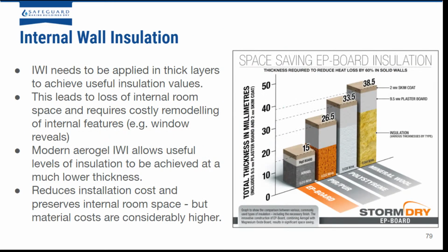good quality ventilation. Okay, so just a brief practical interlude about how to do good IWI. Basically, IWI needs to be applied in very thick layers to achieve useful insulation values, which can lead to a lot of loss of internal room space, and can often require costly remodelling of internal features such as window reveals, doors, etc.